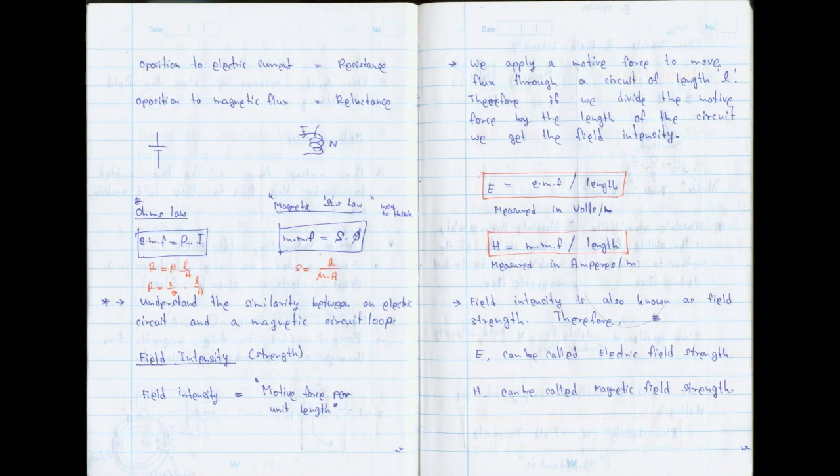When you measure a signal, it is now easy to measure capital E. In the market, you have a gadget called a field strength meter. A field strength meter has a little antenna. You have to tune that antenna to the signal, then it will indicate how many volts per meter strength you are receiving. So that is the real practice. Now this is the theory. In practice, there is a gadget in the market called a field strength meter, and you should be able to work with that if you are a telecom engineer.